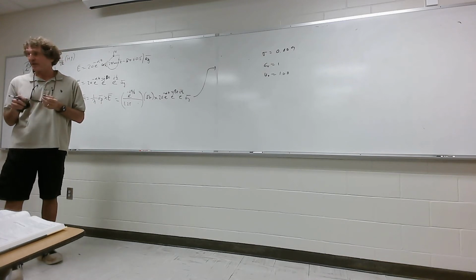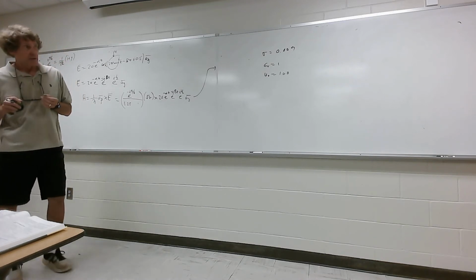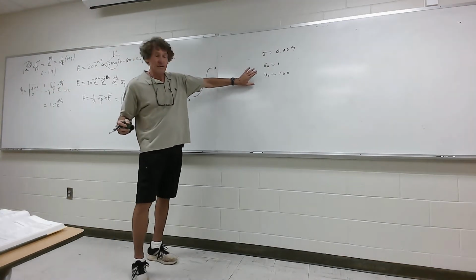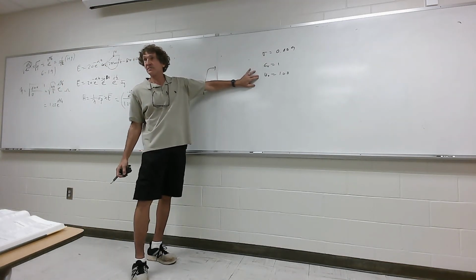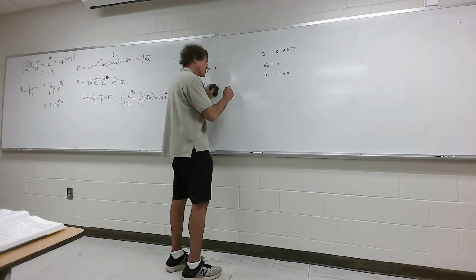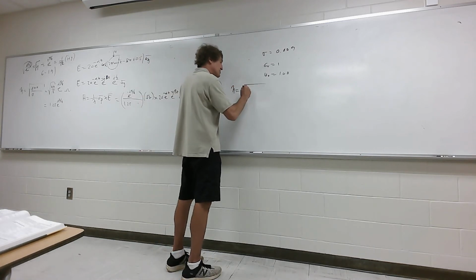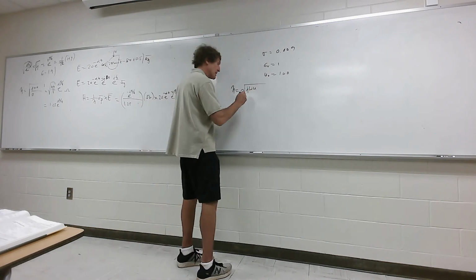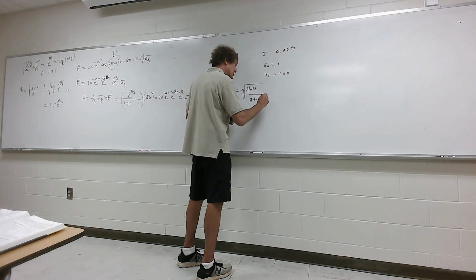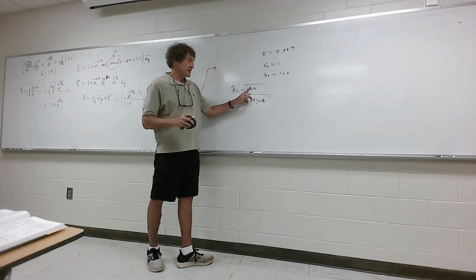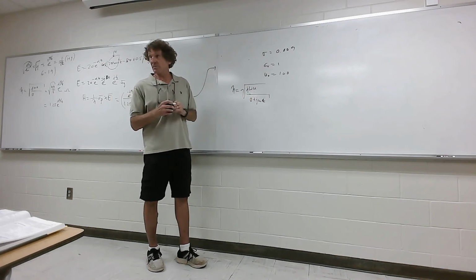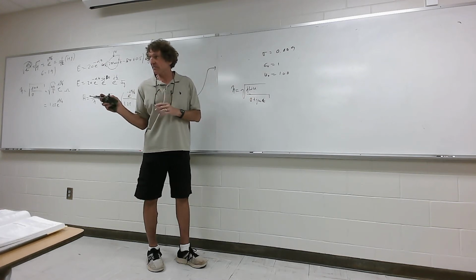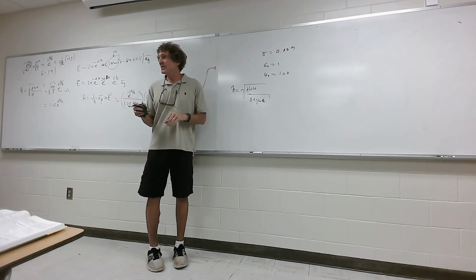I forget what the difference was, but I think they're on the same order. I believe they are, but here's the wild one. See that mu relative? How is that gonna cause problems? Magnetic field. It's gonna also change the value of eta, because remember, eta is equal to the square root of j omega mu over sigma plus j omega epsilon. Now that's mu naught times 100. Well, now all of a sudden, the square root of 100 is 10. That's 10 times what it would be if it was non-magnetic. That's significant, and that's probably the thing that causes your answer to look a little weird.